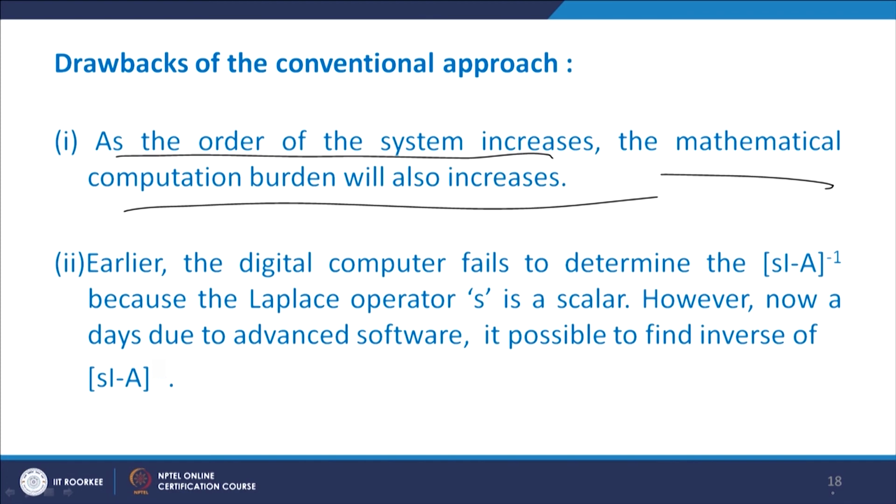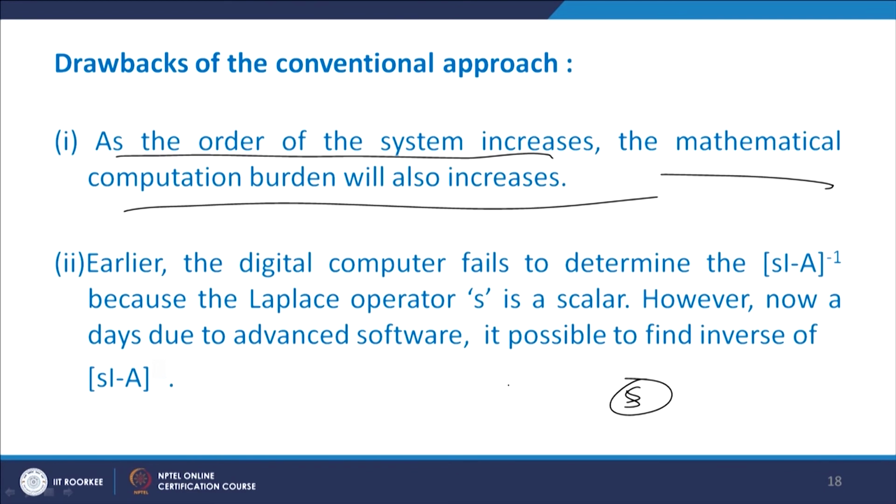And second is that, let us say you want to determine the transfer function from the given state space model by using MATLAB software. In that case we have to take s as a variable, so s is a scalar. Earlier it was difficult to calculate the SI minus A inverse by means of MATLAB.